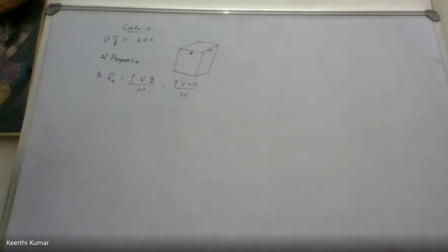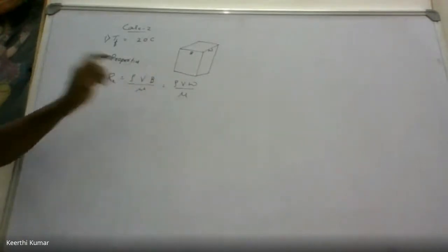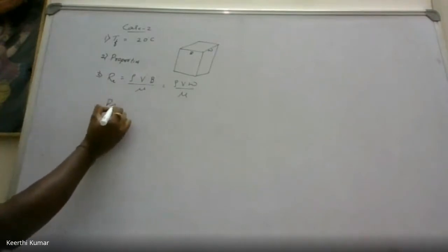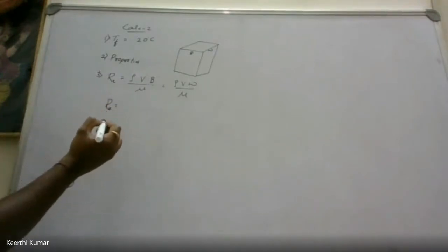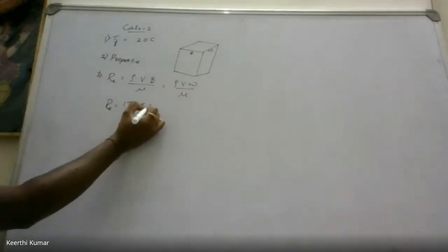So what is the Reynolds number we got for this arrangement? I got the velocity. Rho is how much? We did this yesterday already, using rho v d by mu. Now it is a square, so we will take rho v b by mu. Re is equal to 176540.5.